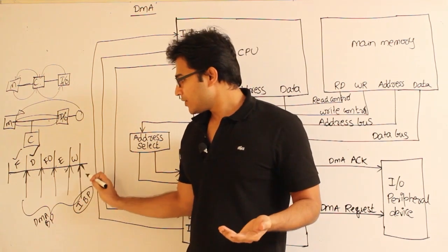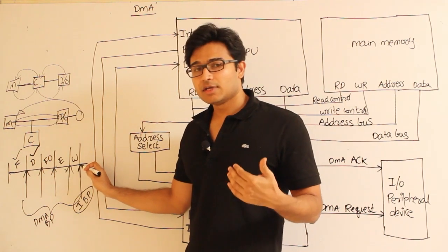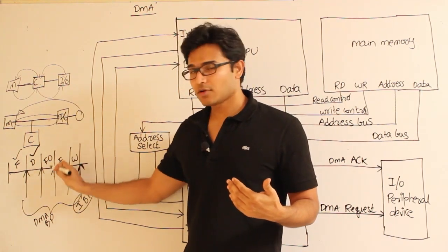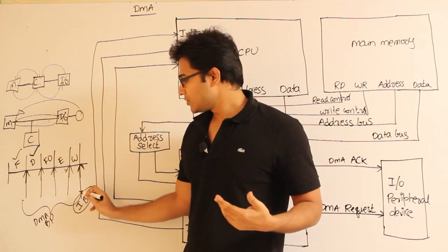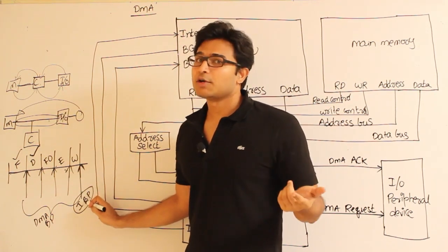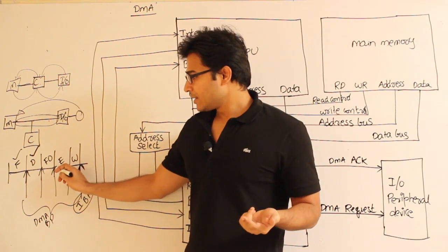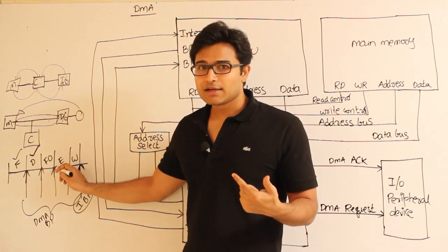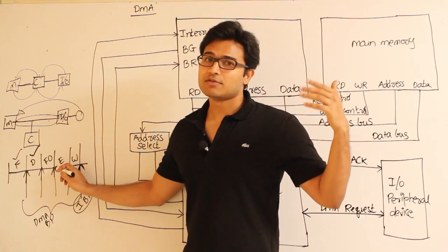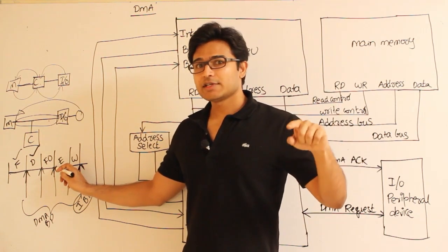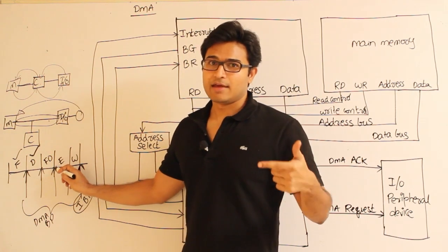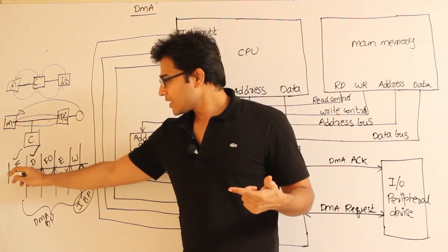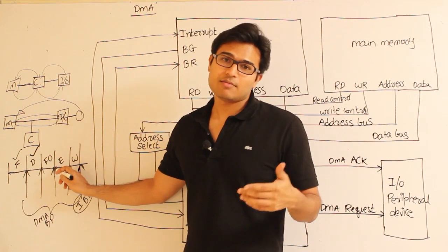But when you stop the execution of an instruction to provide service to an interrupt, many things may go wrong, because when you stop in the middle and start the interrupt service routine, there is a chance that your interrupt service routine will change the registers internally, because of which whatever has happened till here for the instruction may be lost.